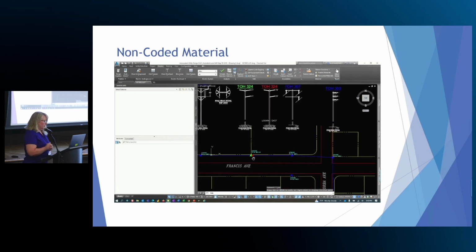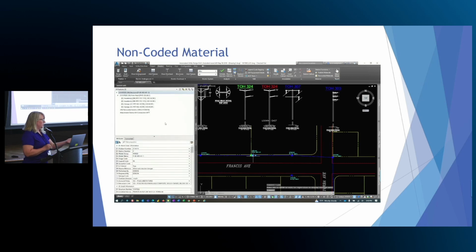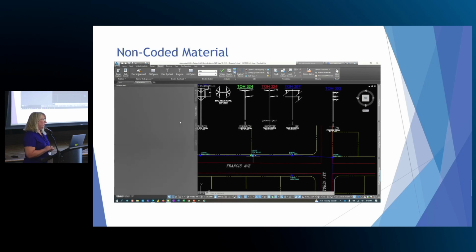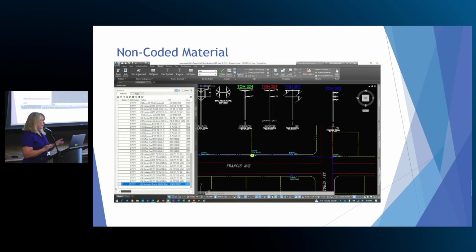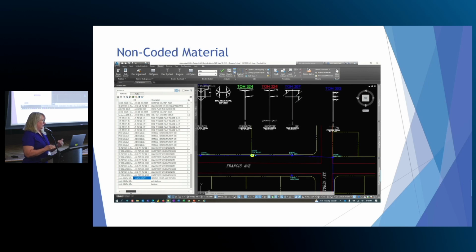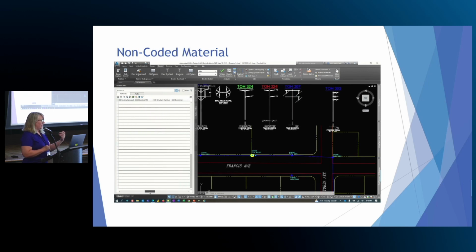My pan was not working for whatever reason, so I have to do it manually. I reselect my station 2. You can see that the CU is in the station, and in material editor, we can check, and it shows that the generic CU is in my material. If I open up to see the child items, you can see the pole delivery and the backhoe, and scrolling over, you can see the price and the total price that gets added into the work order and then, when material is published, sent over to Design Manager.